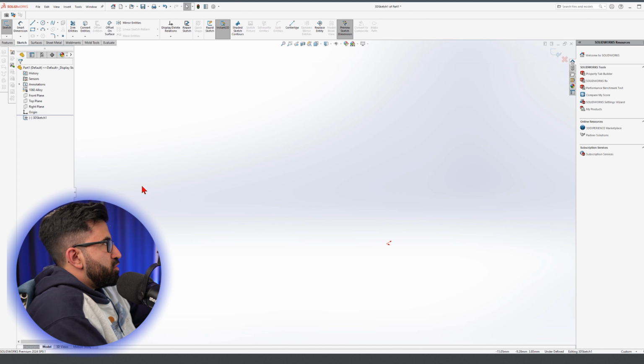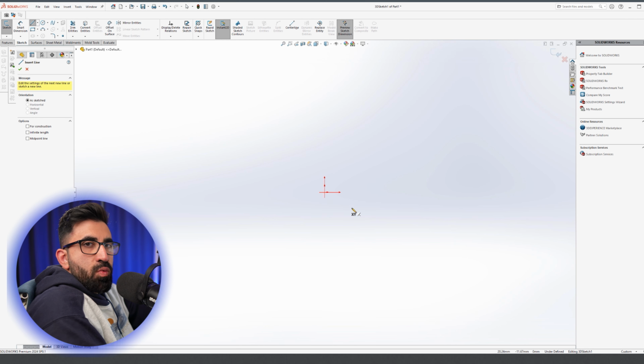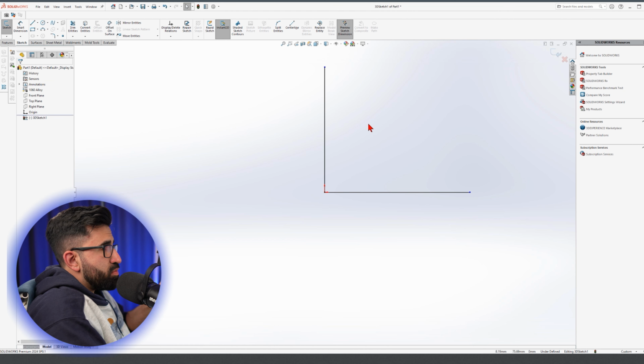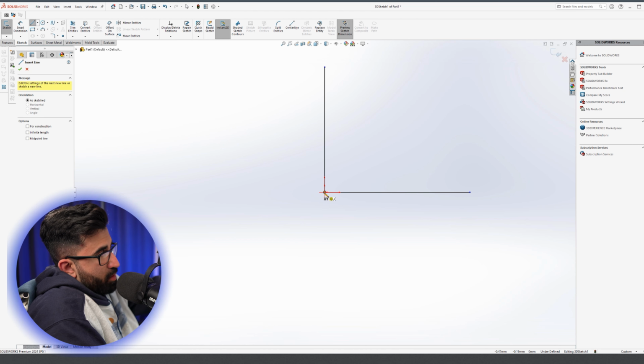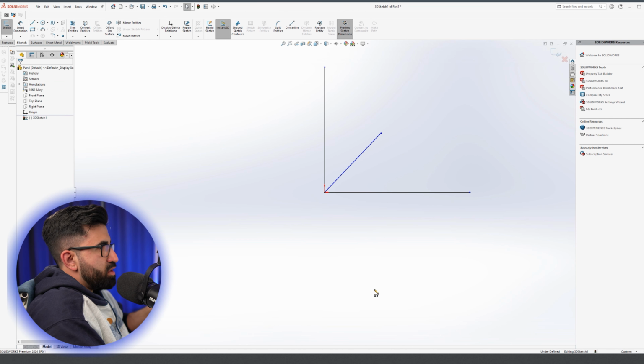I am going to make an example, and I bet you get it wrong. Look, this is the XY plane. It even says next to my mouse cursor, this is the XY plane. If I click here and draw a line, go to the right, it would be on XY, and go up, again, it would be on the XY. Now, I want to go into the depth. I want to draw a line that goes in depth like this. So this is the XYZ, okay?